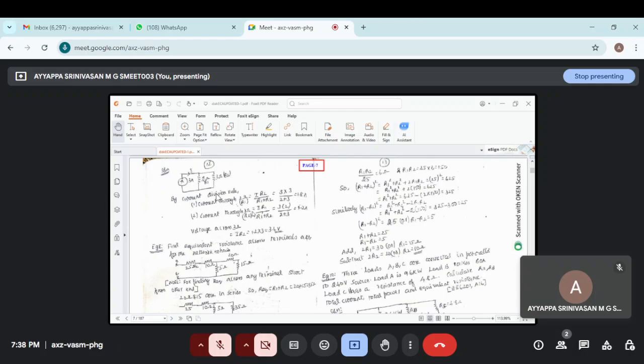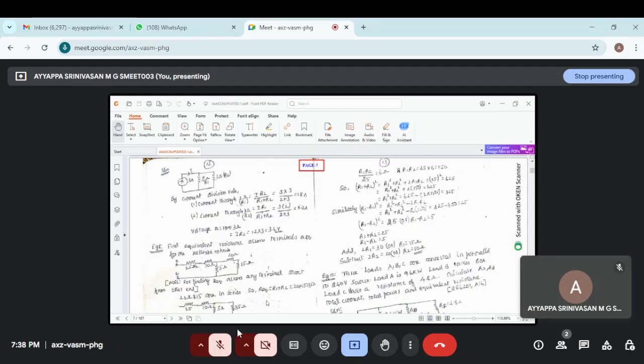We have been given a problem in this way: find the current through each resistor. So 3 ampere is flowing through 2 ohm and 3 ohm. Find the current through each of them. To find the current through 2 ohm, it is R1 and the other is R2. I R2, 3 into 3, 9 by R1 plus R2, 2 plus 3, 5. 9 by 5, 1.8 ampere.